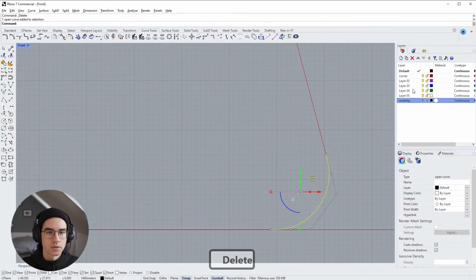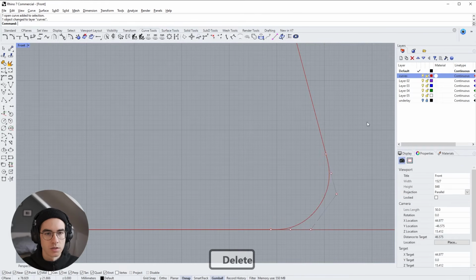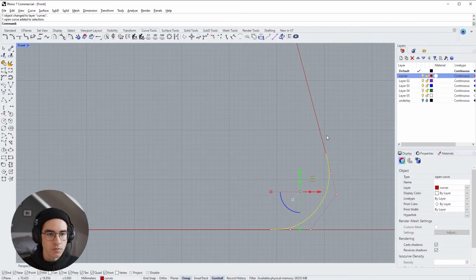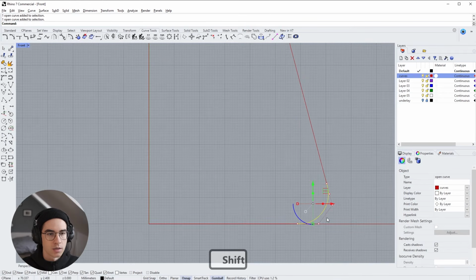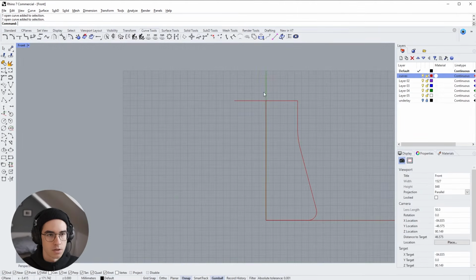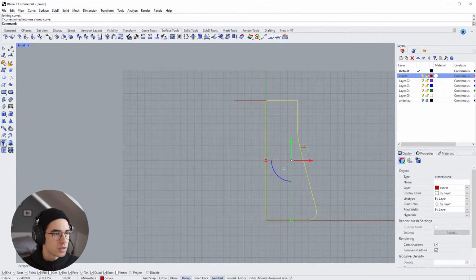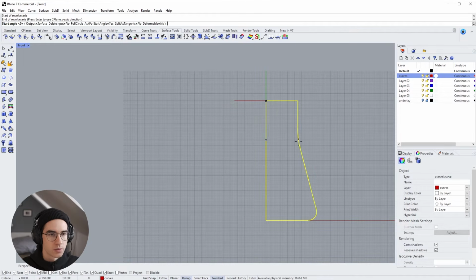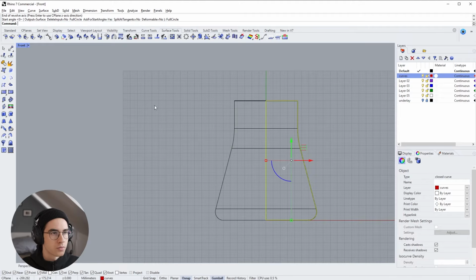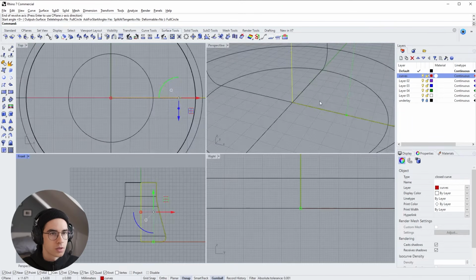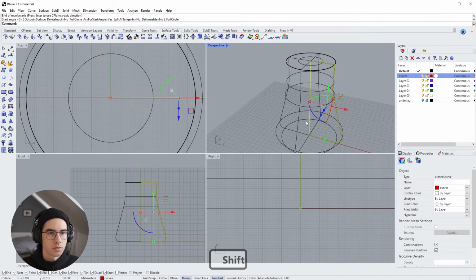Go to the curvature fillet and right click to change object layer. So now this is our curve blend. Okay. Now I'm highlighting all of this. Go to join, and for creating this body, I'm going to go to surface tools. There's a tool called revolve. And I'm choosing the revolve axis and click full circle in order to make a full 360-degree circle.